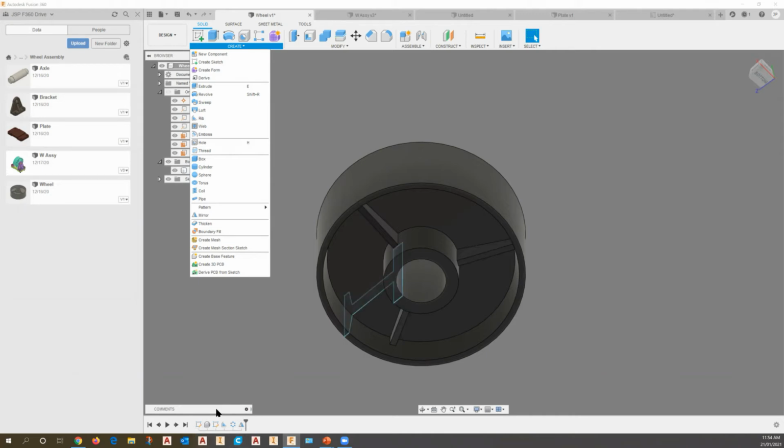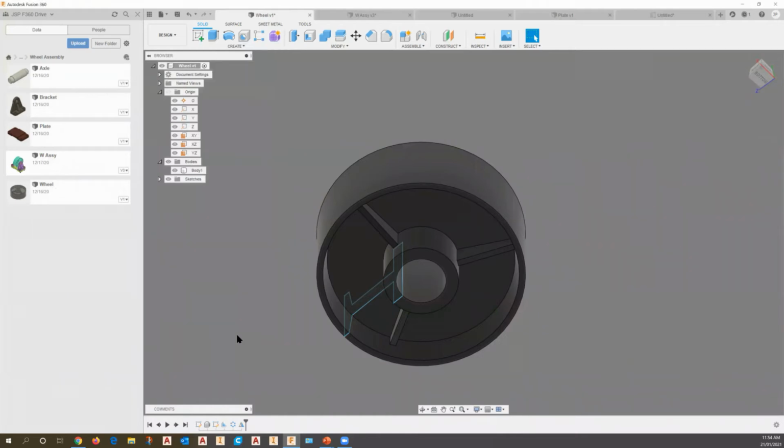The timeline itself will only record the information if you have a particular setting switched on to capture the design history. There's 2 ways we can turn this on. And look, I would encourage you to have it switched on at all times, because obviously if we do that, we can always come back and edit any of these features. You'll notice with the timeline, I can move backwards and forwards here. I'll come back to this in a moment.